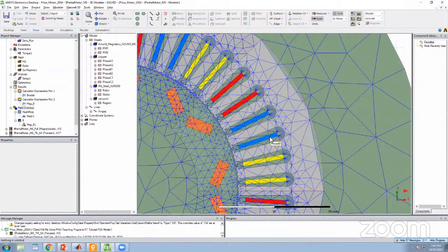Then to make it converge, it needs to increase the number of triangles, meaning refine the mesh by 15%, and then recalculate the energy. Let's say the new energy becomes 50.01. Then the error is smaller than 0.5%, so it can be considered a converged model.